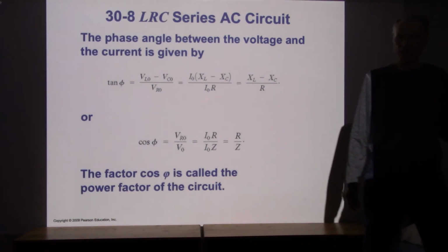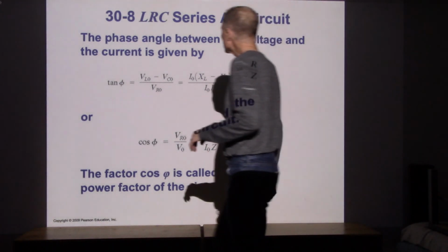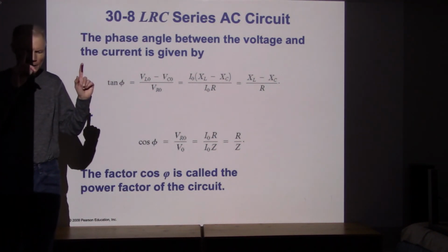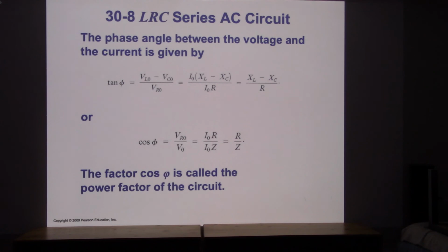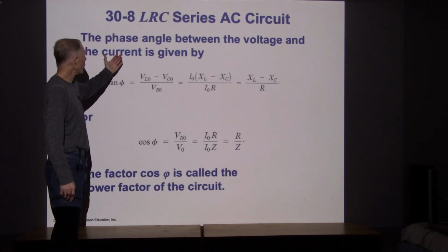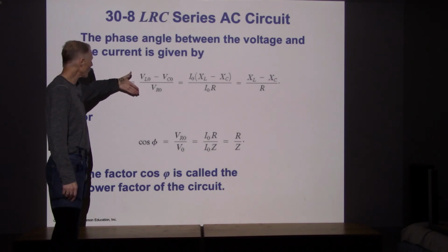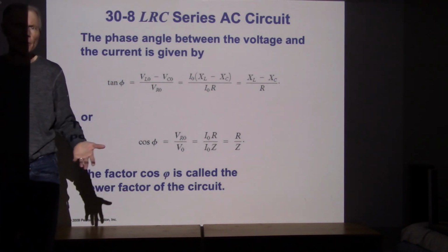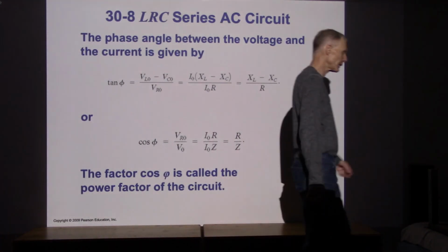Now what you do have to be careful with is you've got to keep the signs straight on the angles. The phase angle could be anywhere between plus 90 and minus 90. Depending on how you enter numbers, the sign should take care of itself, I guess. But be careful. If I'm in quadrant 1, then the angle is defined to be positive. If I'm in the lower quadrant, the sign's defined to be negative. So make sure you keep signs straight, and we can also calculate phase angles.